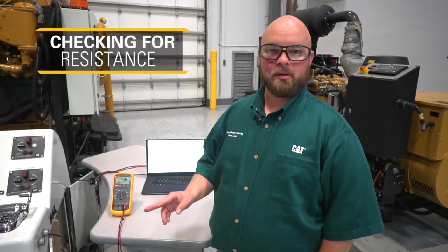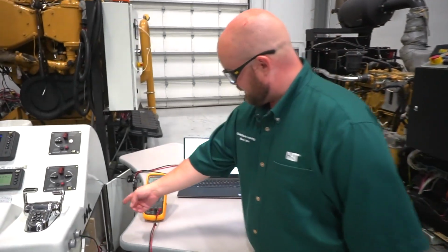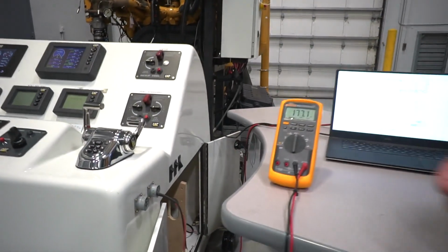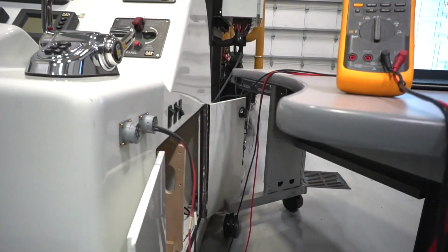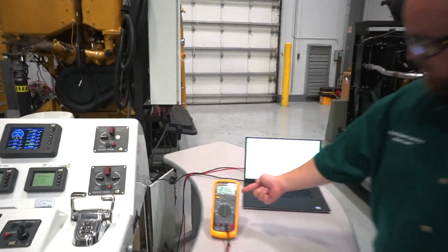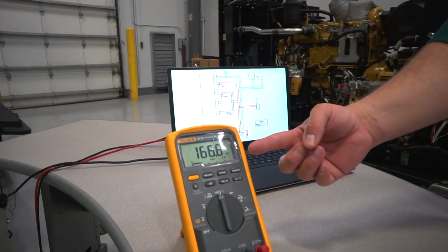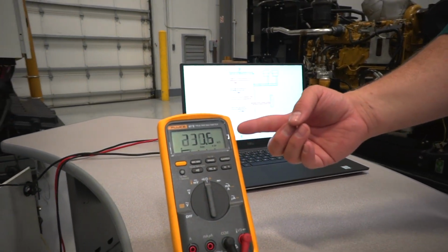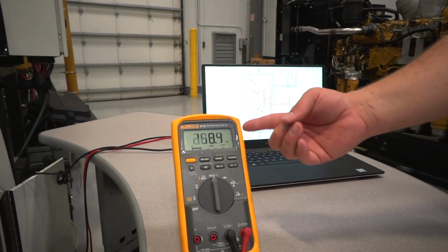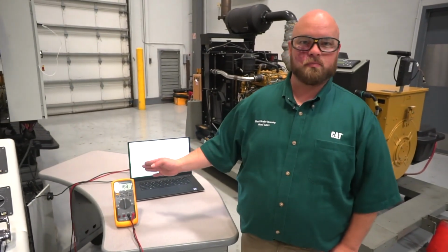All right, so let's look at checking for that resistance of our terminating resistors. We said the 120 ohm resistors wired in parallel, we should see around 60 ohms of resistance. So right now I've got that here. I'm down on my service tool connector and I'm on my CAN plus and CAN negative, right? F and G on my service tool connector there. And if we see measuring resistance right now, we said we should see 60, but we're seeing like K ohms, 130, 200, like K ohms of resistance here, and it's bouncing all over the place. That is not what we expected at all.